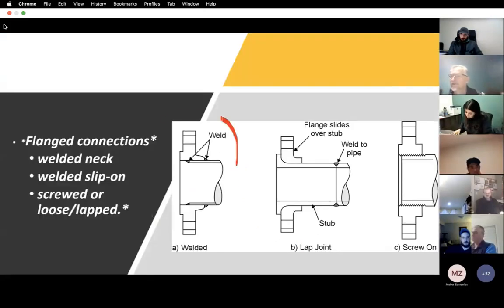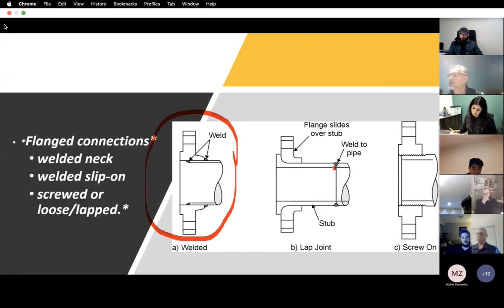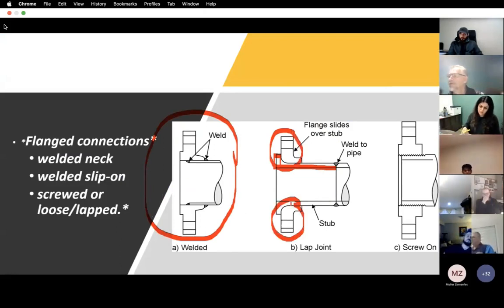And there we are. There's a welded flange welded onto our piece of pipe. Here's something called a lap joint. So we welded an end onto the piping that has a flange. And this loose flange is on the outside diameter of the pipe, and it moves around and rotates so that we can have an easier time of lining up our bolt patterns.